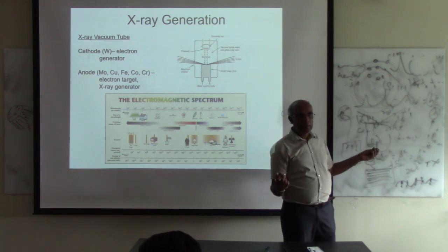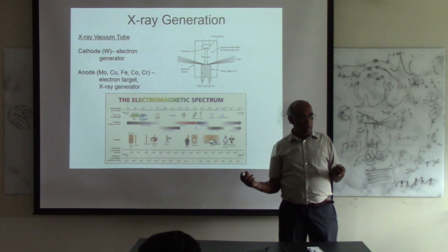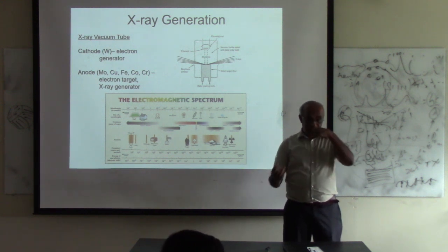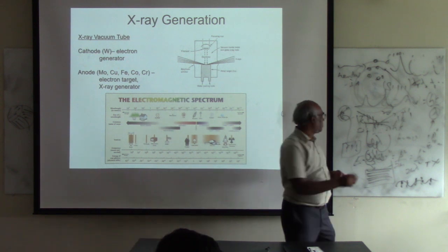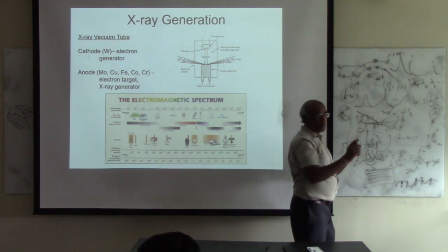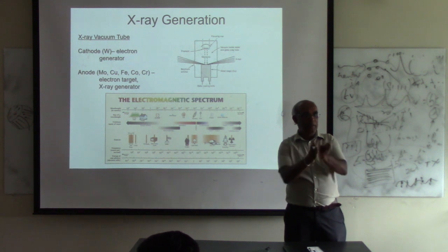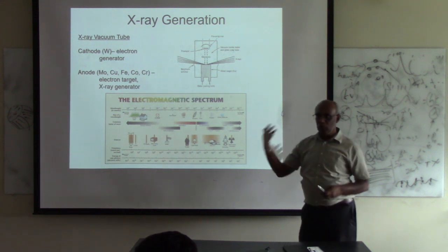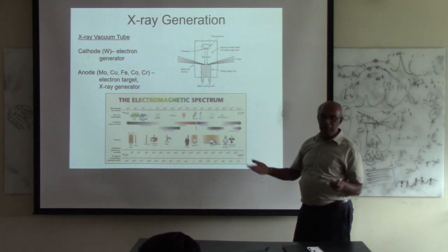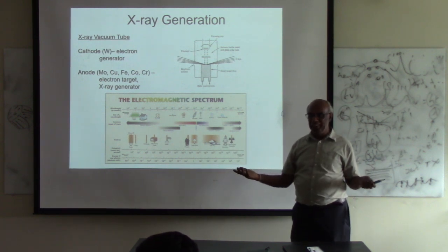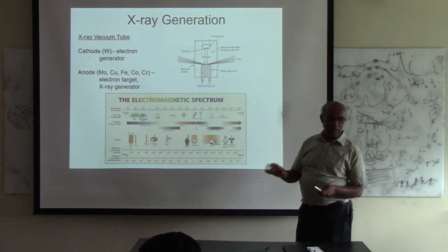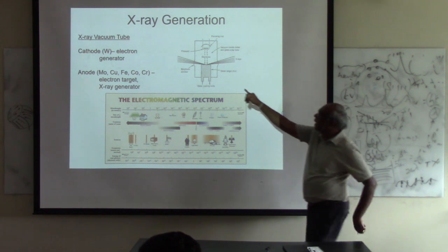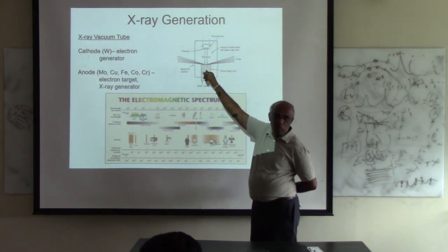Another one is to apply a very large voltage. We call it field emission. Remember, in the old days your TV was so big, where they had the cathode ray tube, right? You have to apply something like a kilovolt potential to make that electron pass through. So that's called field emission. Another way is photo emission, right? If you shine high energetic light, you can make it, but that's not very practical. Typically, you can have either field emission or thermionic emission.